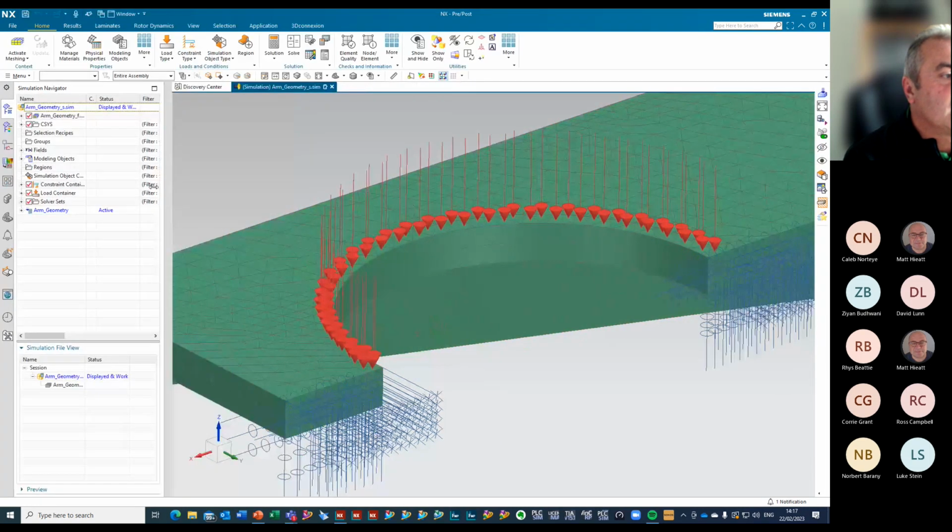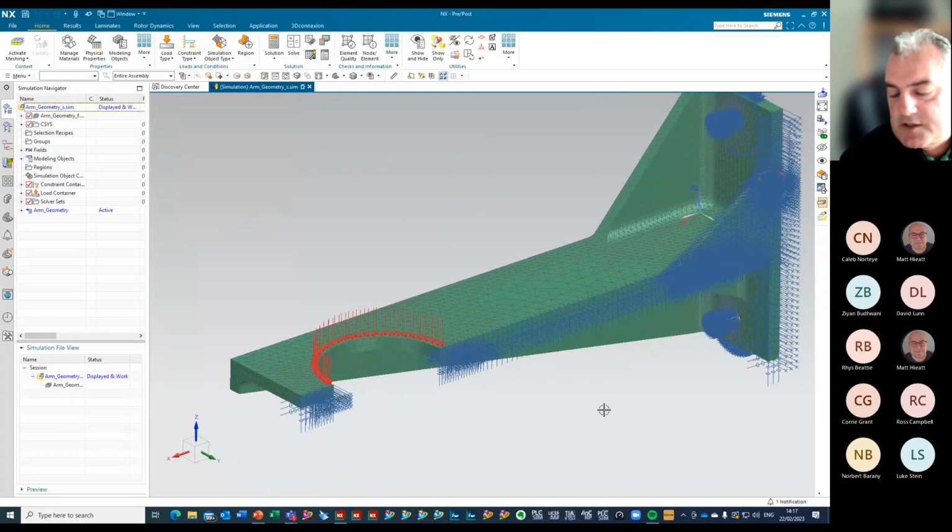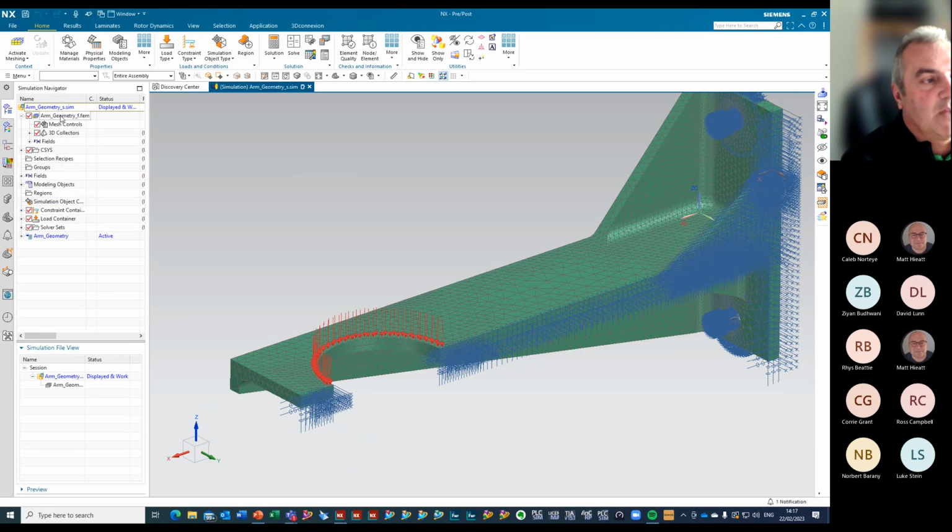If you had the result that we finished with last week, with the mesh adjusted to give us something within the tolerance that we wanted to solve for, you could just extend it from that model. What I've done for this one is I just took that result and exported it as a Nastran bulk data deck and then created a FEM and sim. So here we don't have any geometry underneath this FEM. This is only mesh.